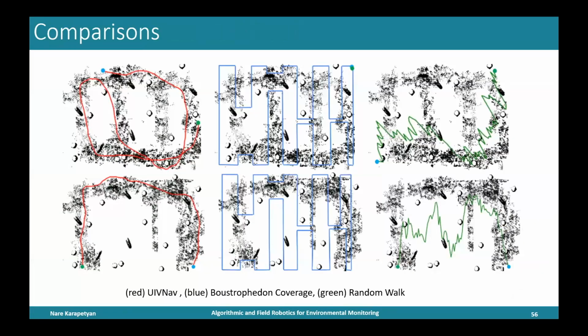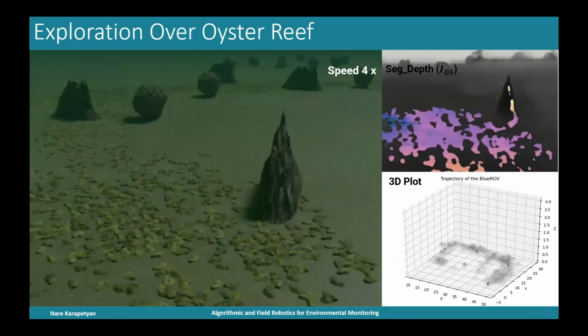So in this one, you are still doing the movement of the robot, but based on the first estimated depth? Yeah, so what we did in the first case, we were training on the raw image. So now we're saying that we don't need all that information. The only thing that we are interested in is where the regions of interest are. That means you have a classifier. And we want to know the spatial information, right? How close we are, whether there are obstacles or not? And that's depth information. So let's just use these two pieces of information, strip down all the domain-specific things and give this to the policy.